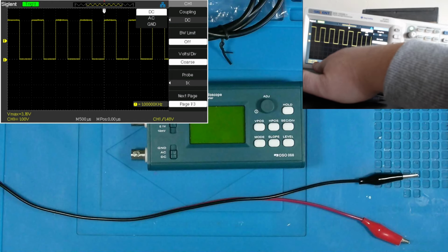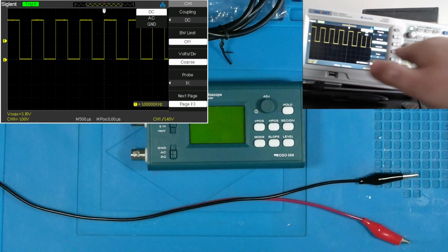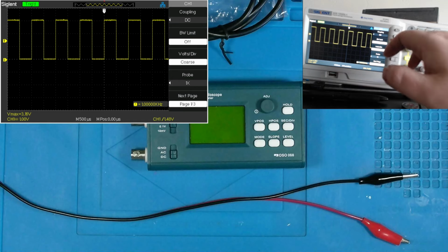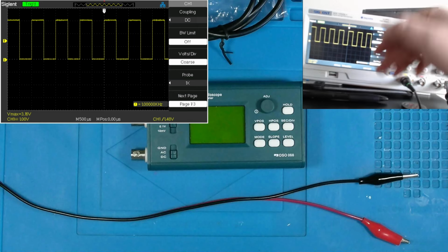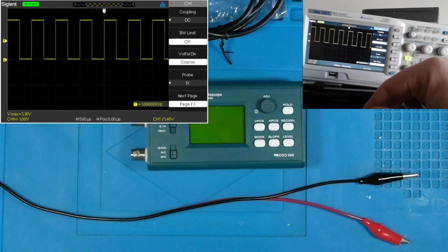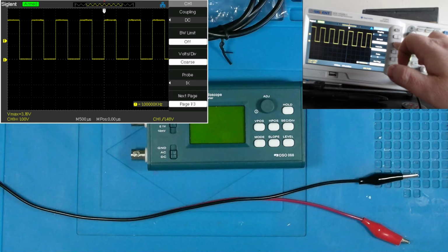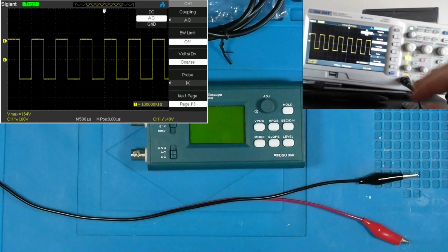Look at my voltage measurements on your math, if there's the ability to do internal math on your oscilloscope. So just something to keep in mind. This is actually not a 3.16 volt AC 1 kHz tone we're seeing here. What we're actually seeing is a 1.64 volt sinusoidal AC waveform.